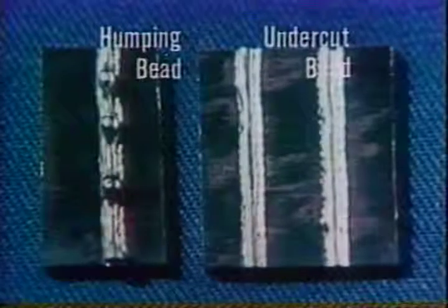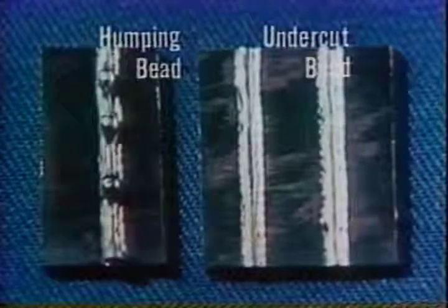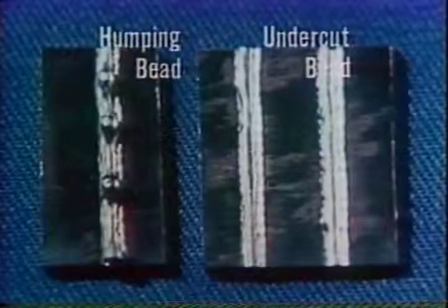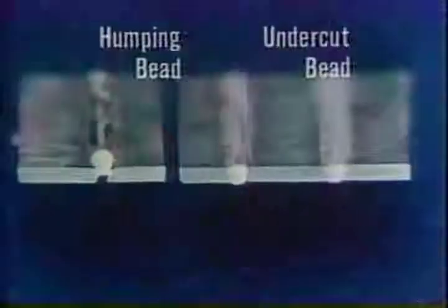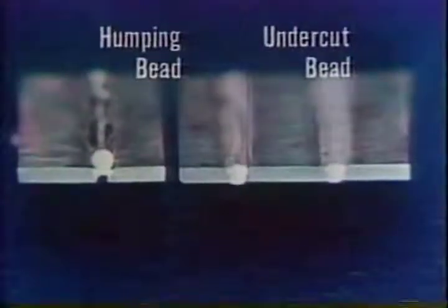It is well known that the high energy density beam can be applied to ultra high-speed welding, but the most troublesome defects in this case are the occurrence of undercutting or humping. Tandem electron beam welding can suppress even such defects very effectively.